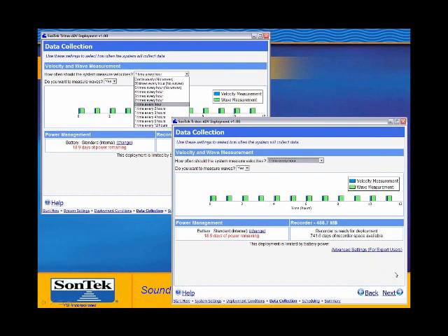Another question here, also from Jessica, is about how long the system can be deployed on external batteries. It will depend a lot on how the system is set up, of course, and how often you request data out of the system. But the typical rule of thumb is that an external battery pack will triple the deployment length that you would normally get without it. Without a battery pack, you tend to get in the range of about 1 to 3 months out of the system.